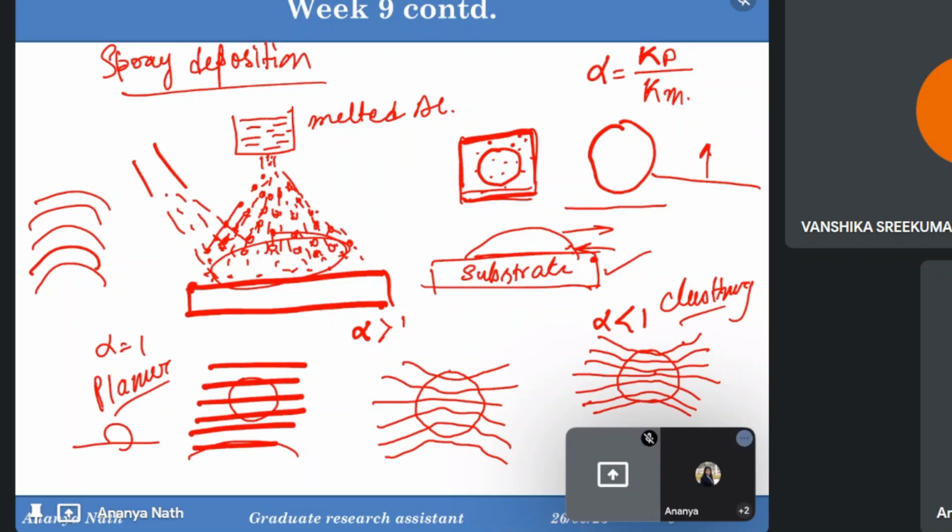Yes, ma'am. Okay. So this is up to lecture 9. So you were having a question of non-heat treatable alloys. Whatever I have seen, there is a lot of work present for non-heat treatable alloy. It's not like you cannot melt the non-heat treatable alloy, but the main difference is you can go for heat treatment. What do we do in case of heat treatment? In heat treatment, we go up to an elevated temperature, we hold the material and then we cool it down. At the time of holding and cooling down, we get the second phase precipitates. The second phase precipitates are properly bonded compounds which give us the strength.